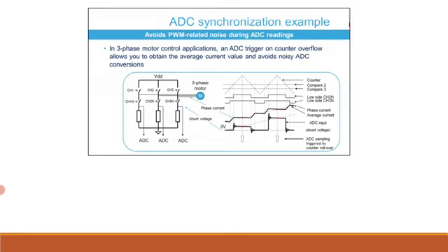It is mandatory to have ADC readings synchronized with the PWM generated for controlling the power stage. This allows extraction of the average value of the current waveform ripple and makes sure the ADC reading is done at an adequate distance from the ringing due to the power switches.